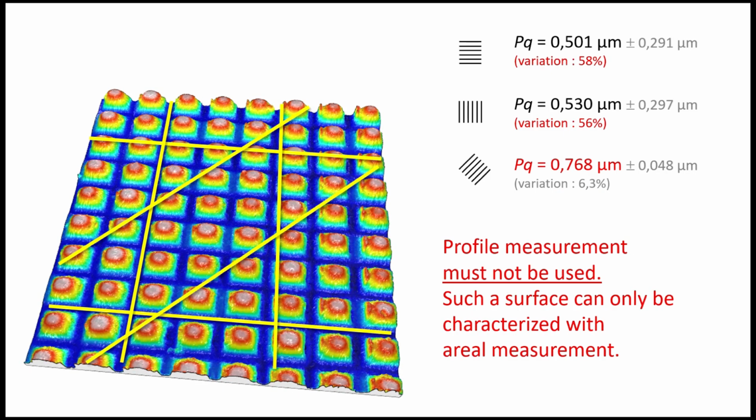Highly structured or patterned surfaces, such as those created by laser texturing, 3D printing, or electrical discharge machining, are deterministic and require areal measurements. Their function often depends on periodic structures or orientation effects that cannot be captured with 2D profiles alone.